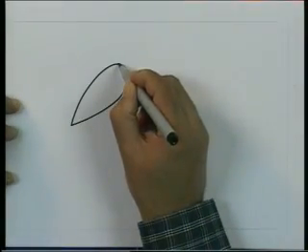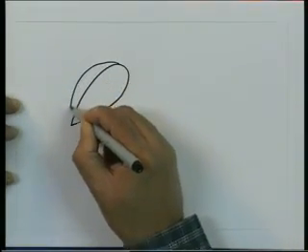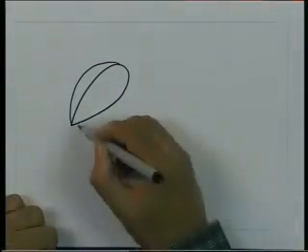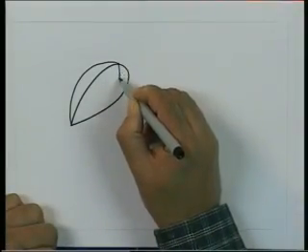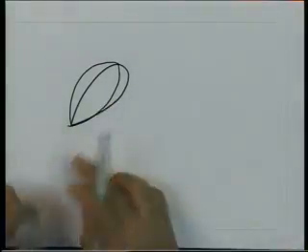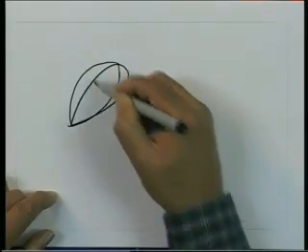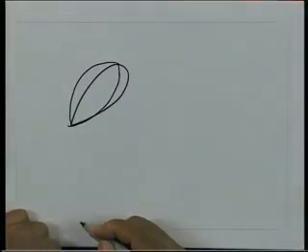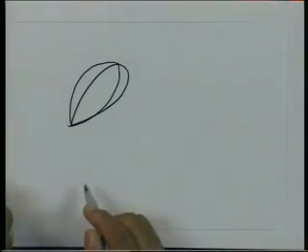In 3 dimensions it will be like this. So, I have one plane, in this plane I have radiation, the half power beam width which is something, the perpendicular plane I have half power beam width, and the side lobe levels are very small.